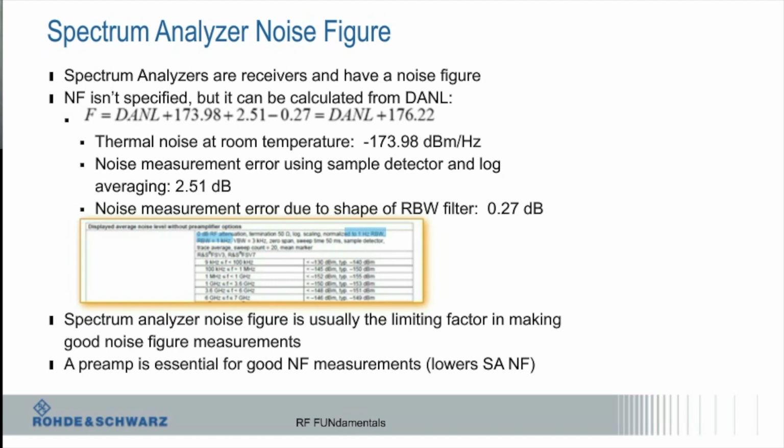A spectrum analyzer, when it first started out, was looking at frequency content, or power versus frequency. How much energy do I have in some specific frequency or band? That's fundamentally what it does. But now they do a lot more than just that. They actually do demodulation. They'll characterize different types of standard-based signals. We can do more generic signals using vector signal analysis, and I'll talk about that a little bit later.